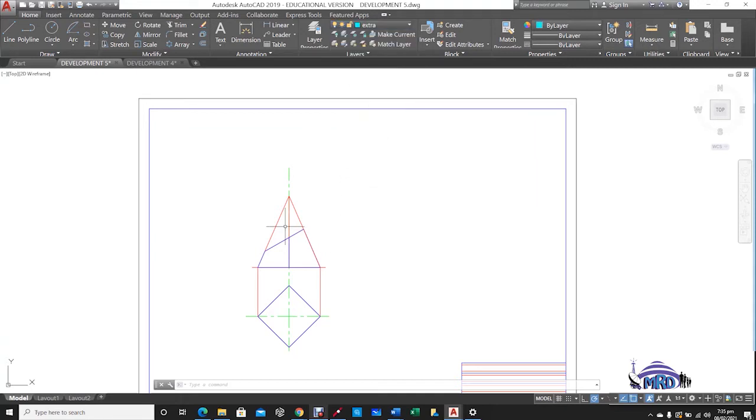So to plot what the cutoff shape would look like in the plan, we would have to drop these 2 points down to the plan. We would need 4 points since it is square. However, in dropping the vertical center line, we can't plot points on that line, so we would need to produce the end view to allow us to plot those points. So we'll do that process in another line as well, and we know the process for producing the end view.